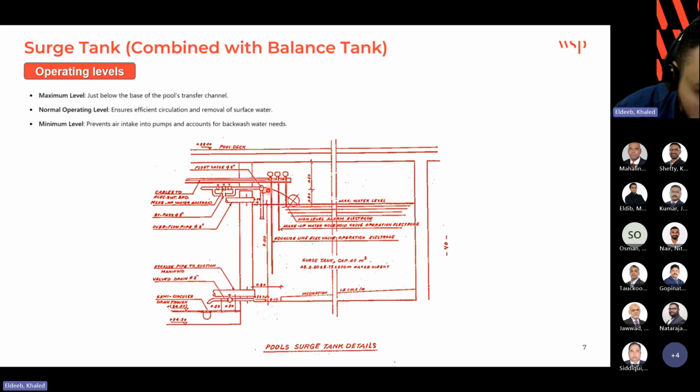Okay, so regarding the float valve here, actually this is not the main control for the water getting inside this tank. We are relying on the solenoid valve here, not on this one. We use this one like a second protection in case the solenoid valve is not working. So this one will close mechanically. Imagine if the solenoid valve keeps open and the water gets inside and the water level goes high. Okay, so this one we can use to close the valve. But actually the main control happens due to the sensors and the solenoid valve.